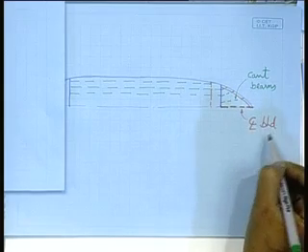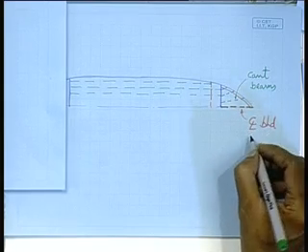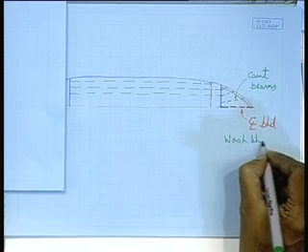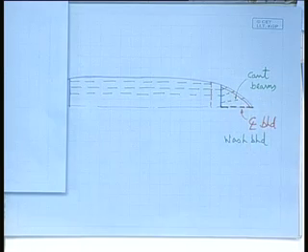This one is a centerline bulkhead. It is also referred to as wash bulkhead, because this bulkhead is not the transverse subdivision bulkhead we have talked about. It is not subdividing the vessel, neither is it subdividing the forward peak into port and starboard tanks. It is just a strengthening member in the center line, so it is called centerline bulkhead. I may or may not give it. It is the designer's option.